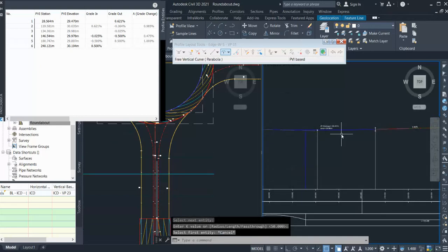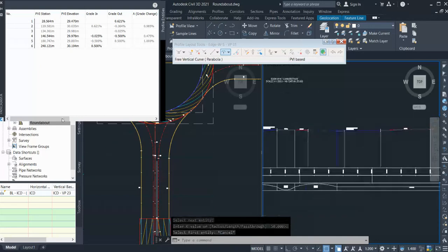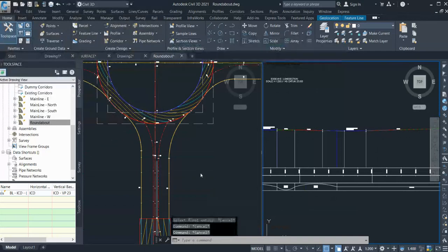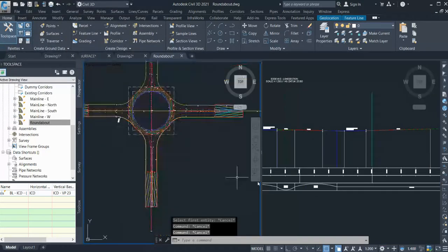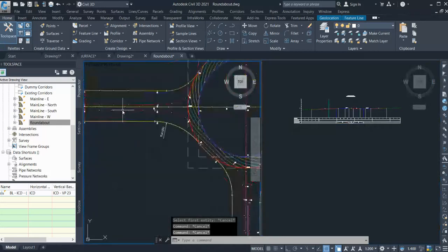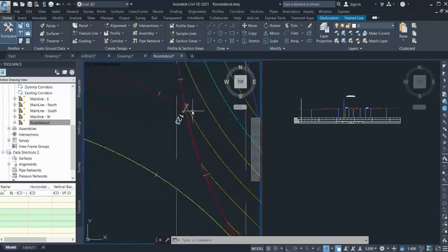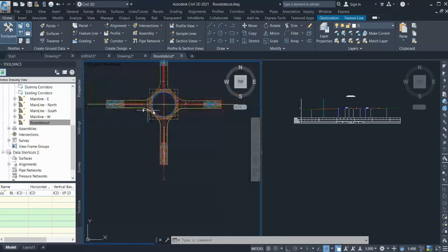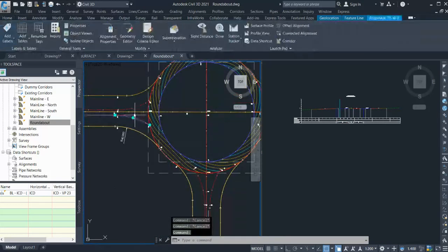So what I did is create some grade. That's why it won't create flat spots, so it won't be a problem with the drainage. I reduced the curve size to 30. Okay, so it's done. My profile for the edge line has been designed. Now I'm going to design my profile for this island, because I have to target it, and I have to keep this level tie-in and the tie-in over here as well. So let's design this alignment now.